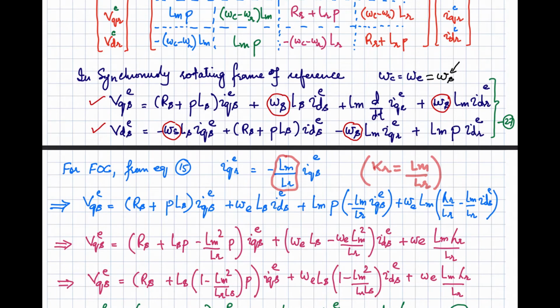So the rotor current of the squirrel cage induction machine can be estimated by looking at the stator current IQS. Now we are going to update these equations, this one and this one, such that they are only dependent on the stator side current, because we can measure that current easily.